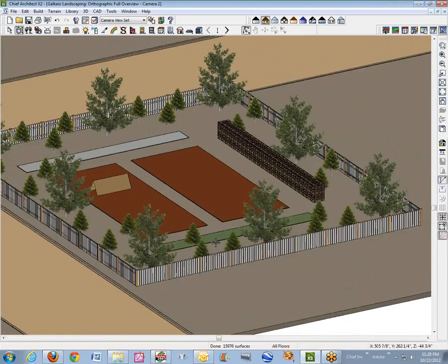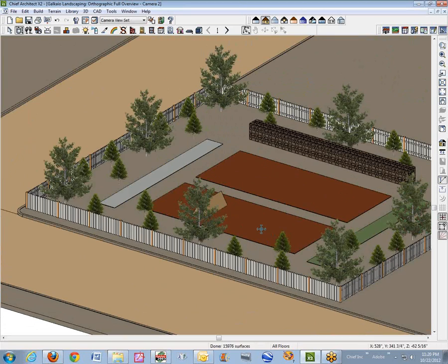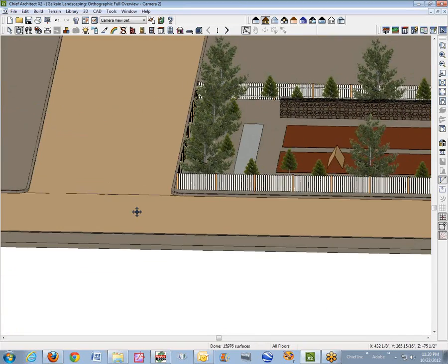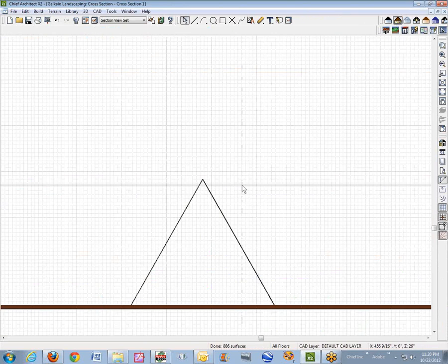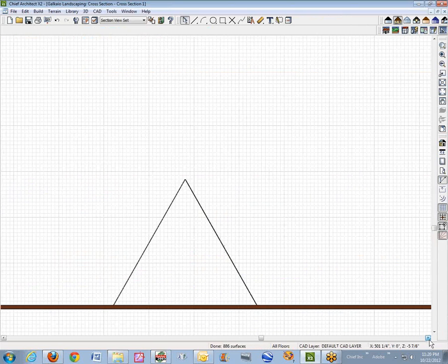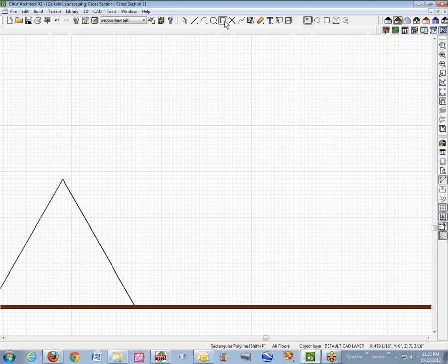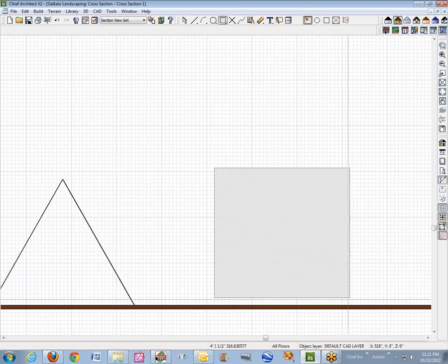You can make simple custom objects like that using polyline solids. You would commonly create a polyline solid in a camera view, like I just did. This isn't the only way you could make one. Let me go back to this camera here. I'll make another one right by it. I'm going to, again, go to Box Tools and this rectangular polyline tool and draw a polyline.